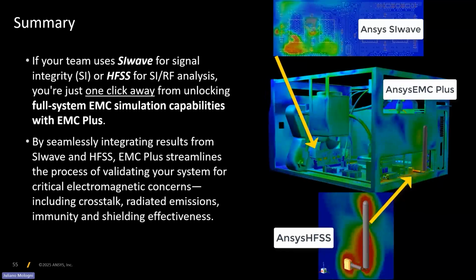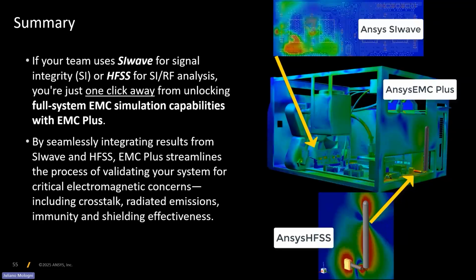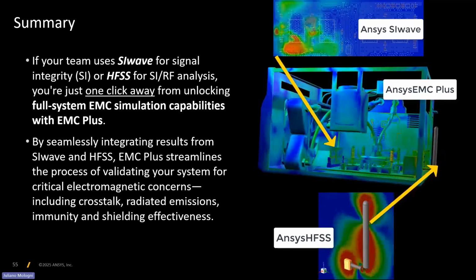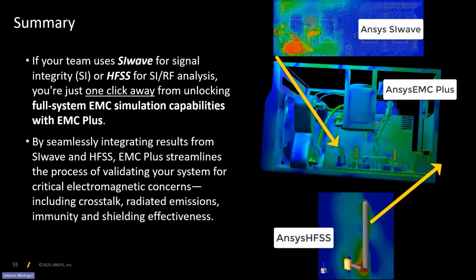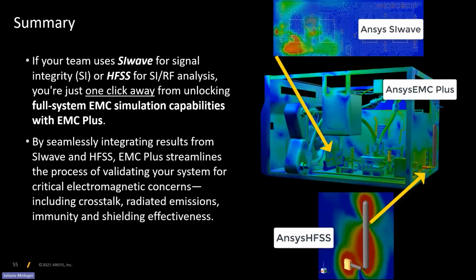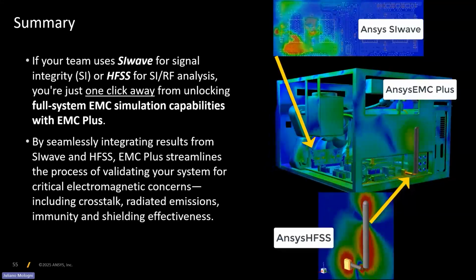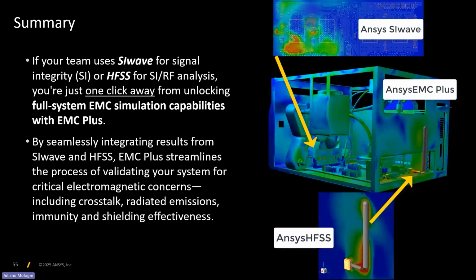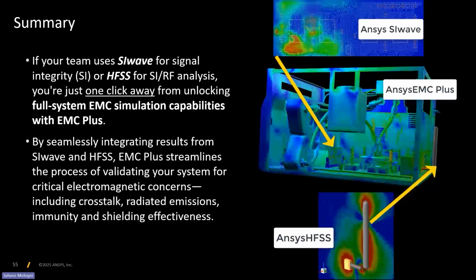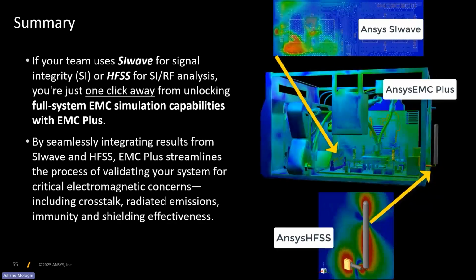If you go to File, Open, Examples, Circuits, there's an EMC folder and there's a power board with the SIwave power board and those switching devices. Basically, we show that you have in Circuits all of your switching devices and your sources. We even have a space vector modulation tool that shows all the three-phase current waveforms for your motor. We have that example, but we have many more. But basically, what you have to do is co-simulate Circuits with either SIwave or Q3D in this case.